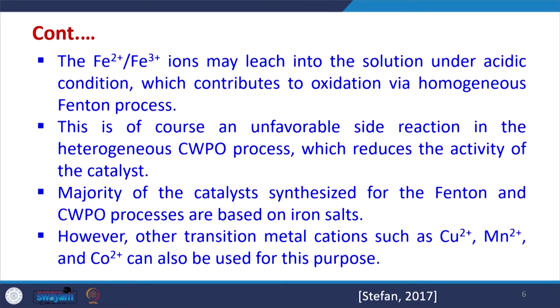Now, the Fe2+ ion, Fe3+ ion or any other catalyst may leach into the solution under acidic condition, and that will contribute to oxidation via the homogeneous Fenton process. This is of course an unfavorable side reaction in heterogeneous CWPO, which reduces the activity of the catalyst, because with time the catalyst amount will decrease and the activity will also reduce.